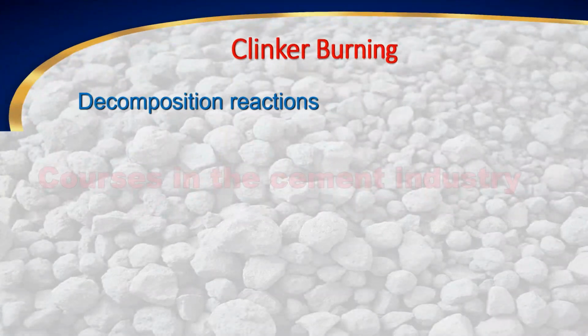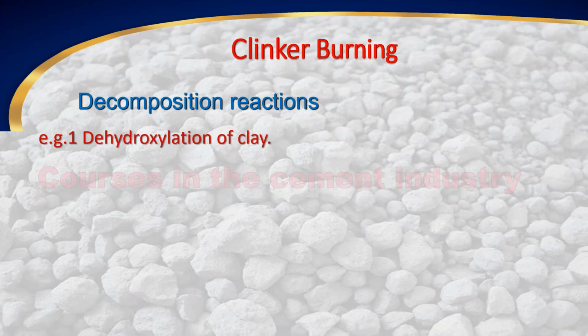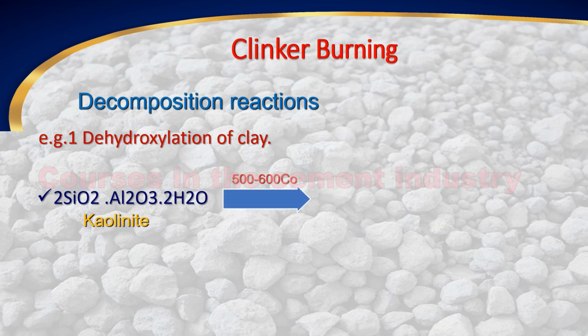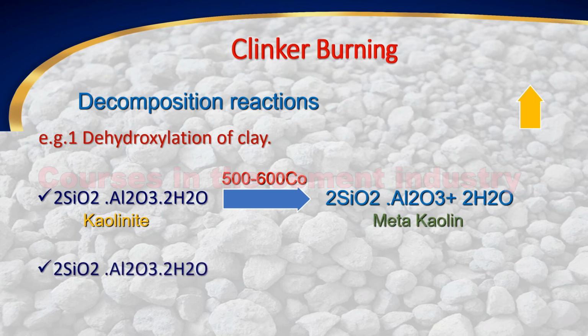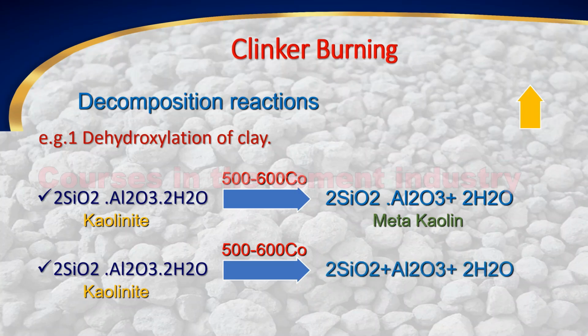Decomposition reactions. Example 1, dehydroxylation of clay. 2SiO2·Al2O3·2H2O, designated kaolinite, at 500 to 600 degrees, results in 2SiO2·Al2O3 plus 2H2O, designated metakaolin.